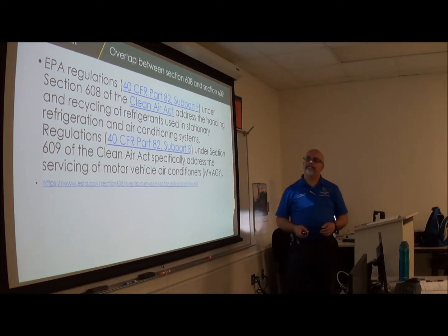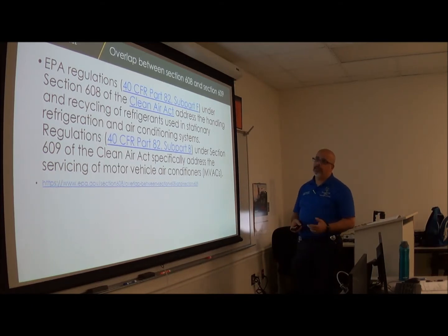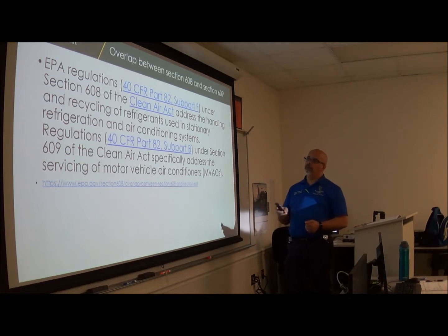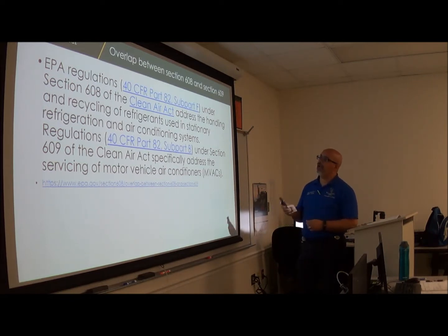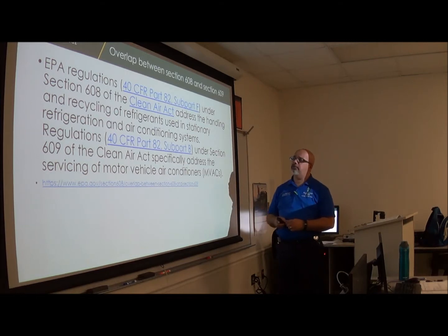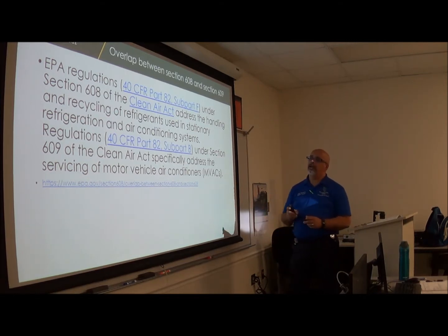Okay? So, the overlap between Section 608 and Section 609. EPA regulations, 40 CFR Part 82 Subpart F, under Section 608 of the Clean Air Act, address the handling and recycling of refrigerants used in stationary refrigeration and air conditioning systems.